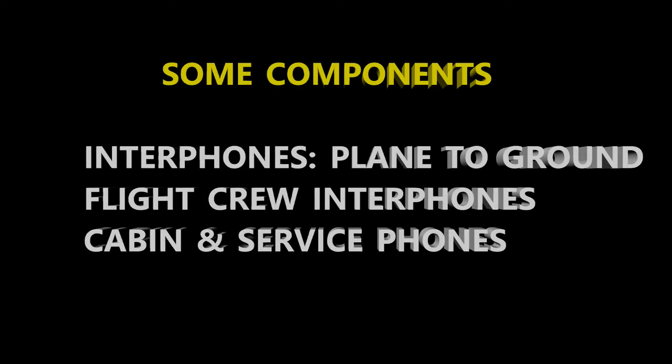Certainly, there's a lot of different things here, but just in general, remember I mentioned the high frequency system. When we're talking about communication, it could be speech through interphone. So we've got a telephone, an actual interphone system of some sort, and that's for speech. You have your interphone system, and that's for the cockpit to be able to communicate to the ground crew.